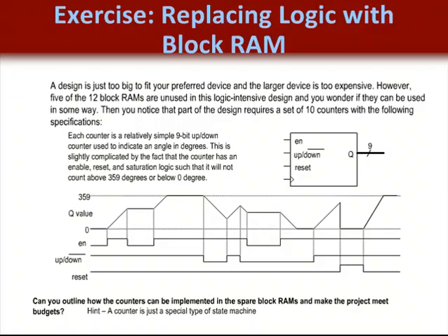This is a question to get you thinking about using block RAM memory in other applications other than as pure RAM and ROM. It may not be the most efficient way to implement a counter, but given the outline of the problem, it is better to use this resource than waste it completely. Remember, it may make it possible to move to a smaller device that has block RAMs, but not enough LUTs.